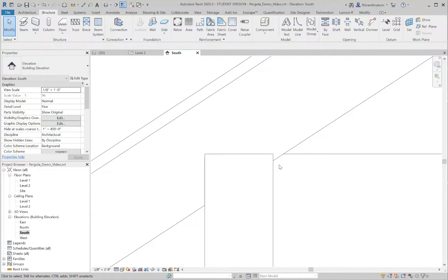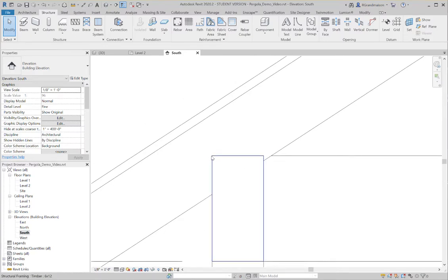So what I'm going to do is move it up so that this intersection that's right here is at the corner of the beam, so these have full bearing. Now if I wanted, say for instance, this to only have a 2 or a 3 inch bearing here and a point on the rafter resting right here when it extends upward, I could use something like a dimension or even a line to do that. Pretty easy to do. Let me show you a way to accomplish that.